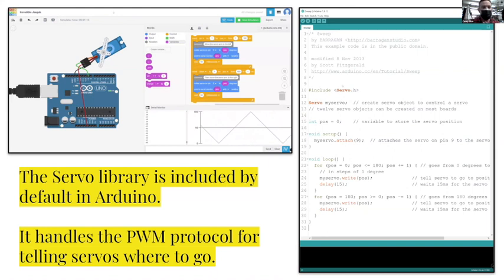There's some logistics to how you tell a servo, I'd like you to go to position 173, please. But the good news is the library deals with all of that for you, so you don't need to learn the exact mechanics for what percent of the pulse width modulation signal time you have to use to get it to a certain position. An Arduino library will handle that for you, and the same is true if you're using Raspberry Pi to drive servos. There's lots of different libraries that will handle the logistics on the very lowest level for you. If you're interested in that, you absolutely can learn those pieces or read this header file to see what they did to make that happen. There's no reason to. For a long time, you're going to have all of the control you need if you just play around with this.